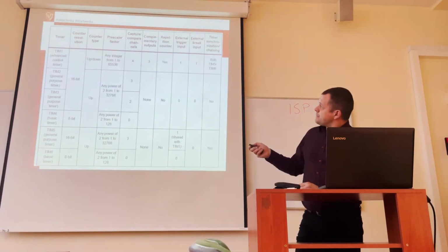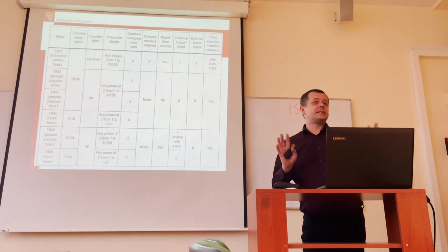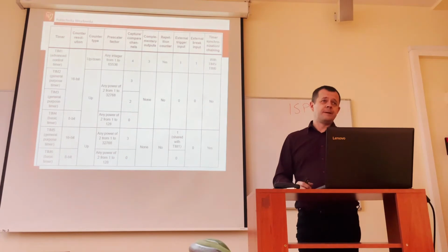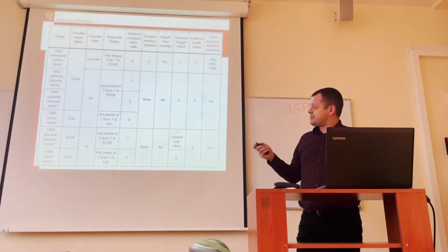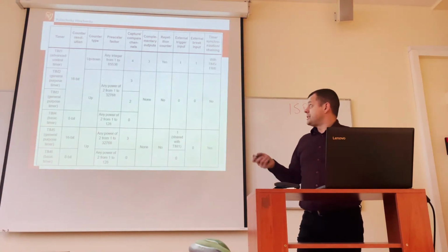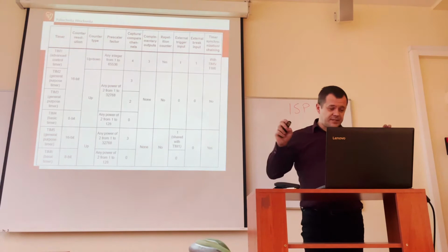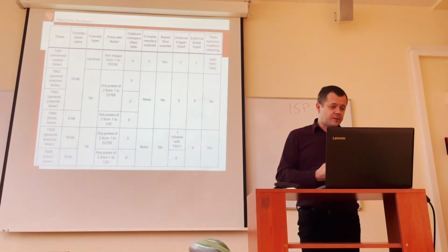Let's take a look at the most advanced one, Timer 1. Not only is the timer 16-bit, but also the pre-scaler is 16-bit, which means that theoretically the timer is pseudo 32-bit, because it's not fully 32-bit. Still, the resolution is a bit extended. In case of Timer 2, 3, and 5, we can expect a 15-bit pre-scaler, and the weakest ones, Timer 4 and Timer 6, just a 7-bit pre-scaler. So theoretically, it's pseudo 15-bit, better than nothing, but not really something super extra.